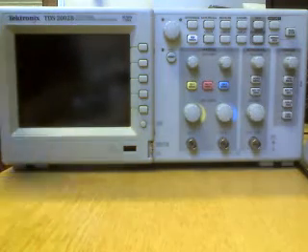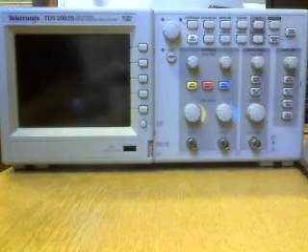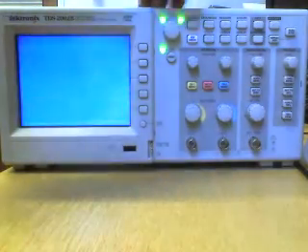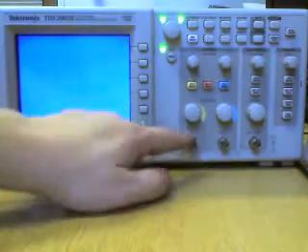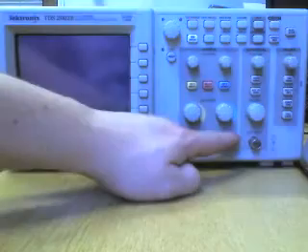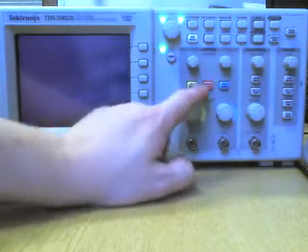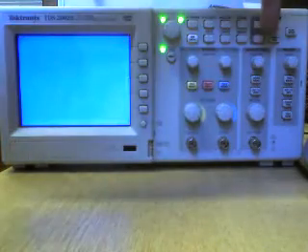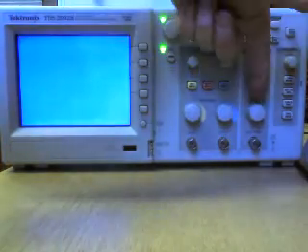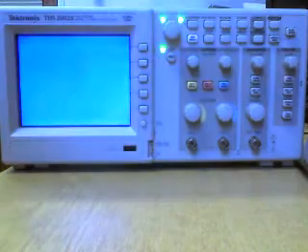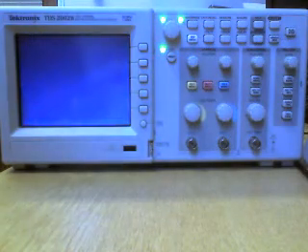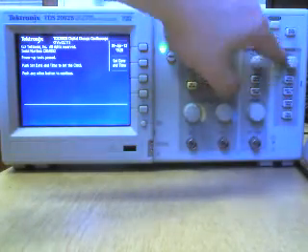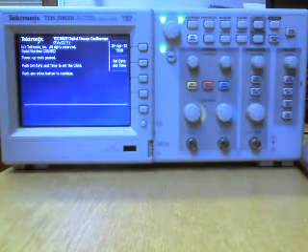So while we switch this on, the power switch is at the top on this one, hit on the way. While it's booting up, it takes a few seconds, we'll run through what we've got on the front panel here. Now we've got channel 1 input, channel 2 input, volts per division for channel 1, volts per division for channel 2, position again, just like on the analog one, horizontal position, and seconds per division. All the controls are the same, and not only that, we also have our trigger, it's down the side here, and our trigger level, okay, which you need to trigger the scope with.